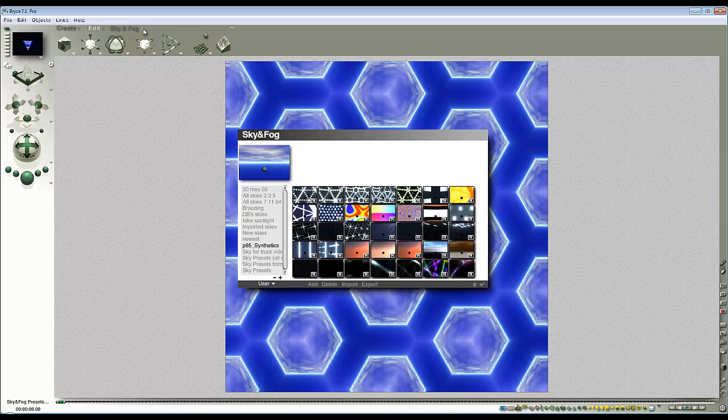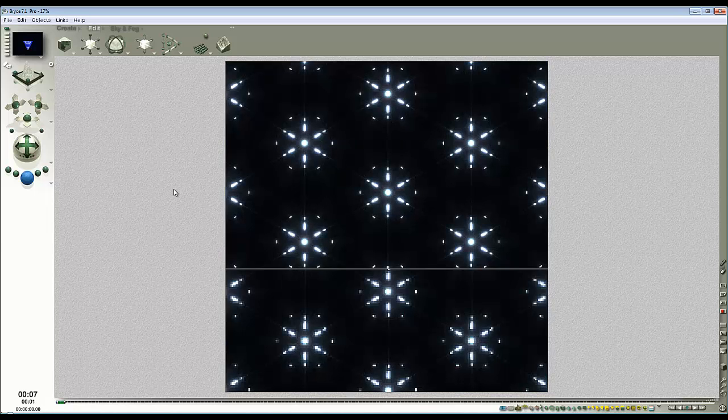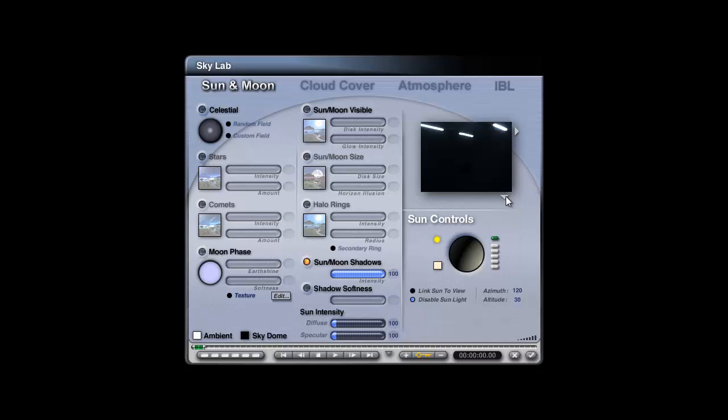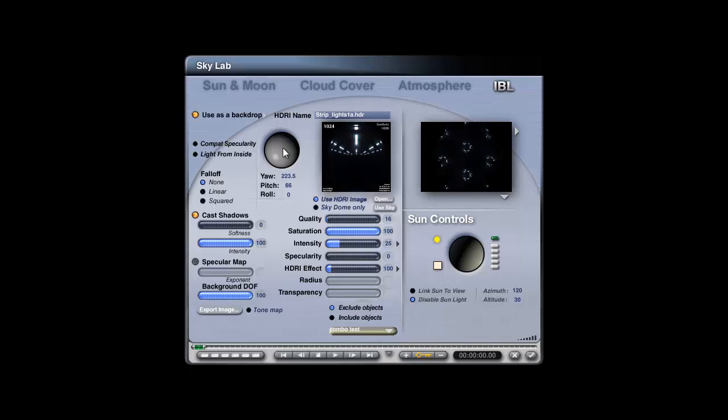The next step is to go to a selection of HDRI images, whatever you've got. I've got a few here that Haro and I have made. They're synthetic, so they've been made in another program. They haven't been captured from photographs. I'm going to select this one, which is one I made and Haro has modified, so it has got a good dynamic range to work, so that's handy. I'm going to use image-based lighting and rendering scene, and I can use the rollerball here to rotate this round and get various patterns. You can see this is actually an almost monochrome image.